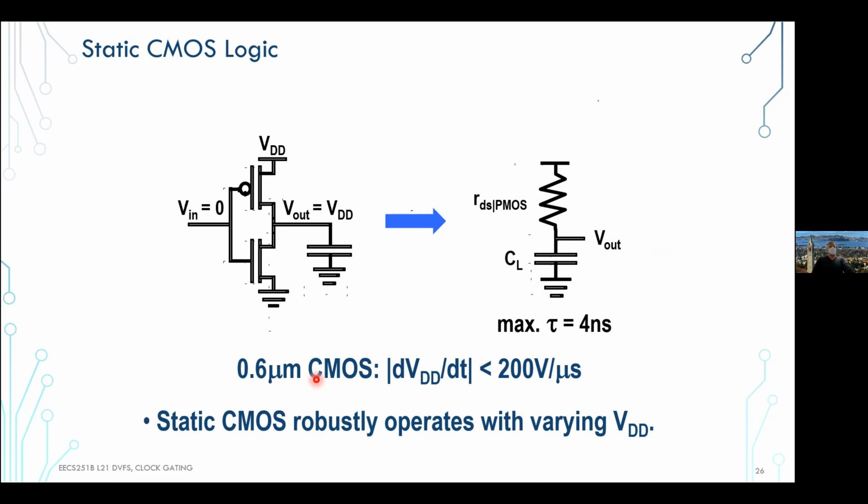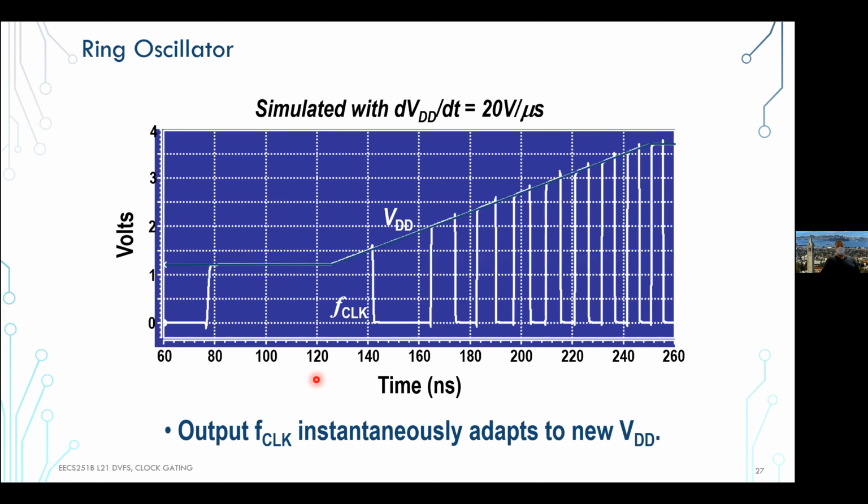you want to look at essentially the dVDD/dt targets, because for a given capacitance of the, let's say, supply, that gives you the ripple. And so you don't want to design your system for low VDD, low dVDD/dt, because at low VDD your transients are going to be slower, right? And then all of a sudden you want it to operate at higher voltage where you don't have enough decoupling cap or even the power supply network to be able to handle now these larger spikes, essentially, right? So you have to make sure that dynamic aspect is basically satisfied. We see that, what we mentioned earlier, the ring oscillator reacts nicely to changes in supply voltage. This is just basically as you increase the voltage, the count kind of increases.